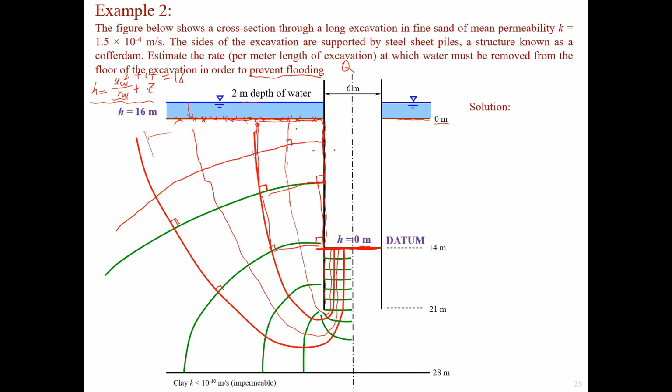That's fine. You will realize when you do the calculation for the seepage, the result will be similar. So when you attend the assessment, as long as your flow net looks reasonable and your result is not a huge difference from the right answer, then you won't lose any marks. But obviously you have to meet the requirements: right angle and square. If we draw some extra lines, we have to get some extra lines for the other one, right?